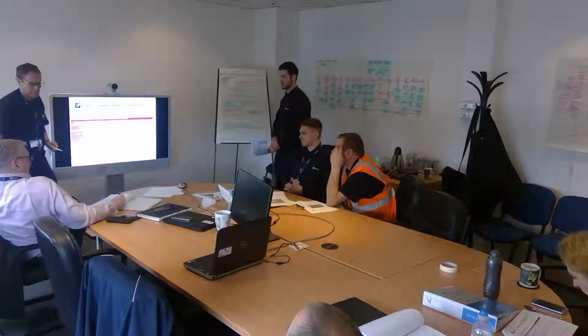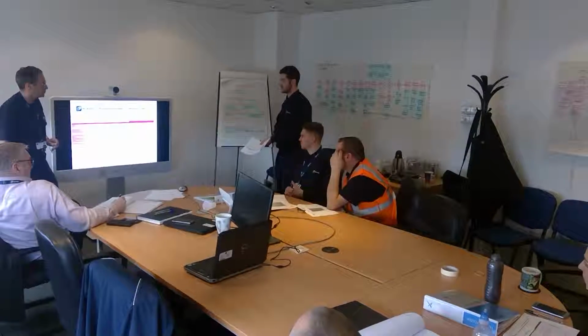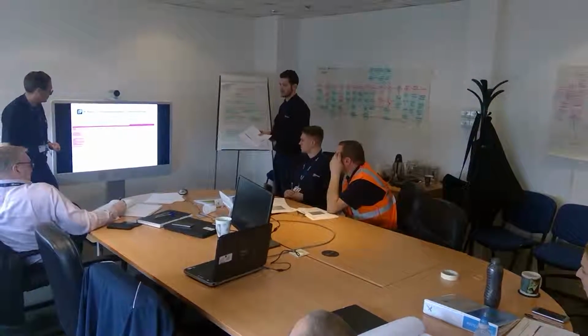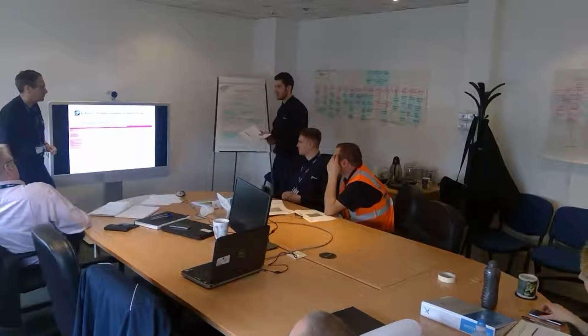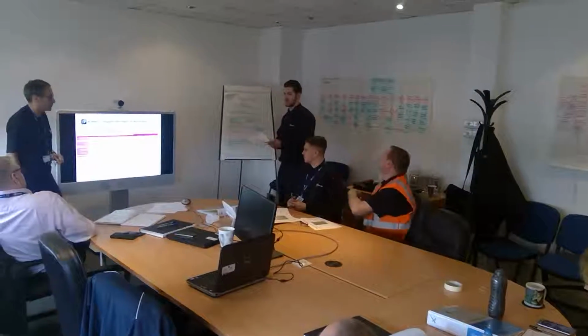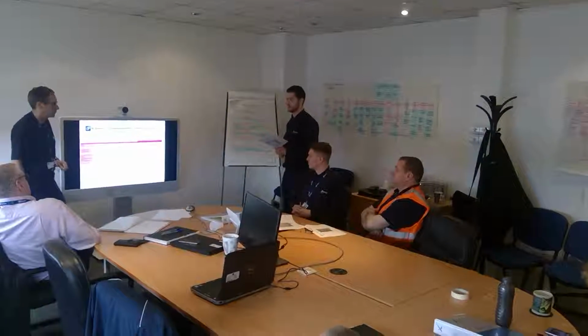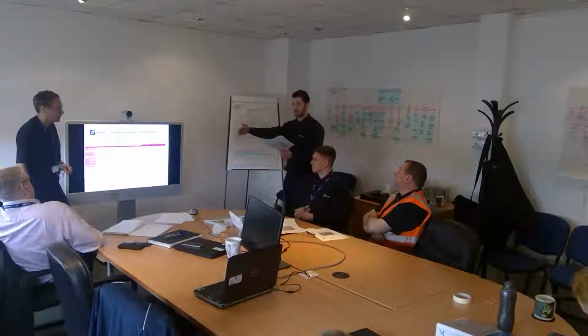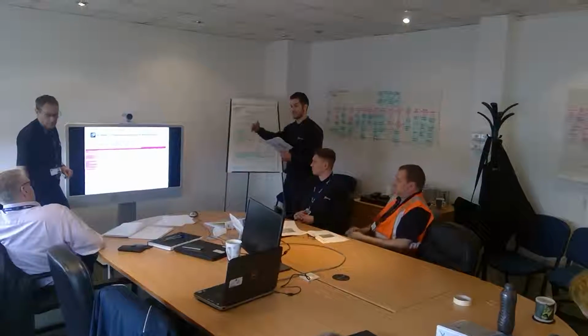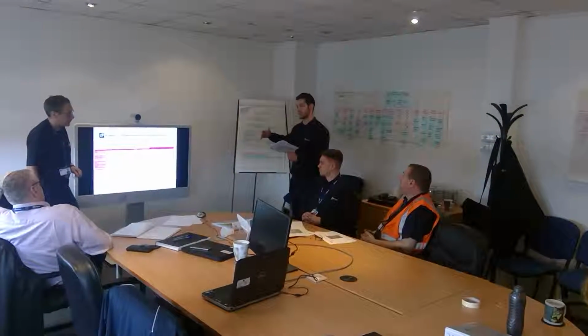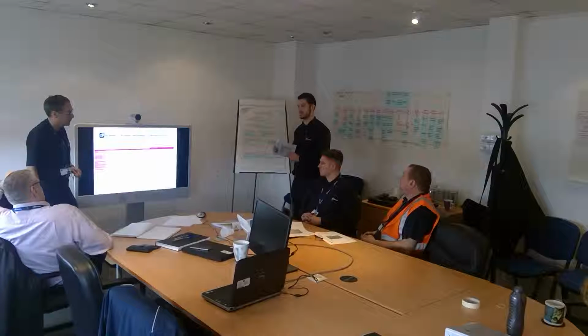Is this a spool? Sorry. This was spools. 12 spools that came with, we put PN16 flanges on them. When you check the boilers, they're actually PN6. So nobody thought to check that on day one, and it could have been stopped. When that gear came in, they could have said, I'll check back at the boilers, I'll check what PN rating they are.